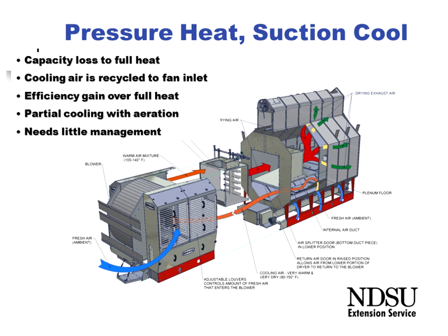That air then is cycled back to the intake of the fan, and that is blended then with outside air. So we're preheating the air that goes through the burner and into the dryer. Capturing this cooling heat can increase the energy efficiency by maybe as much as 20–25%.